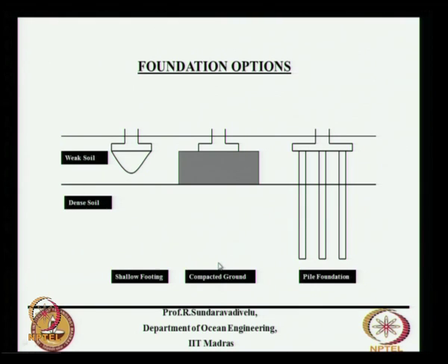So this figure shows what is a shallow foundation, what is a deep foundation. If we have a weak soil, then you have a dense soil, then we have to necessarily go in for a deep foundation, which is called a pile foundation, you go into the deeper soil. This is possible even if you have a weak deposit, maybe 3 meter or 4 meter or even 6-7 meter, you can take it deeper. I have shown in the figure also where we are taking the pile, you have to take care of the negative skin friction in this region,